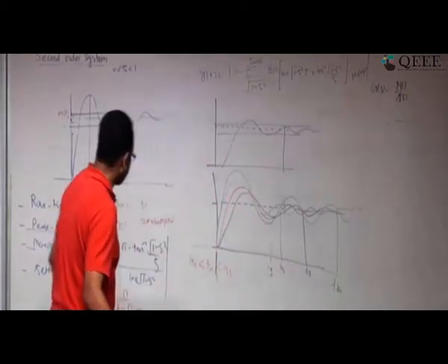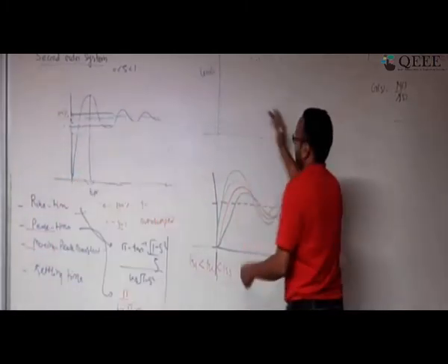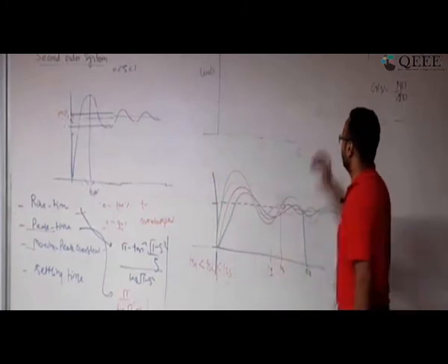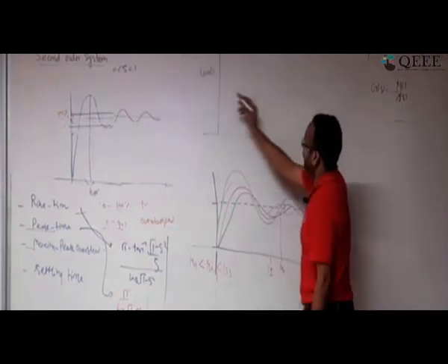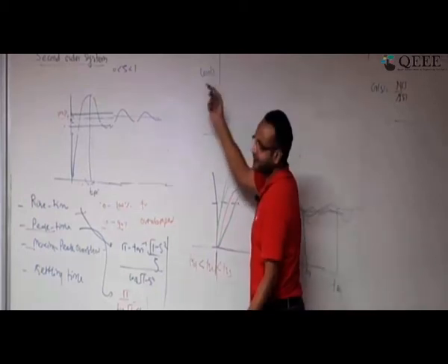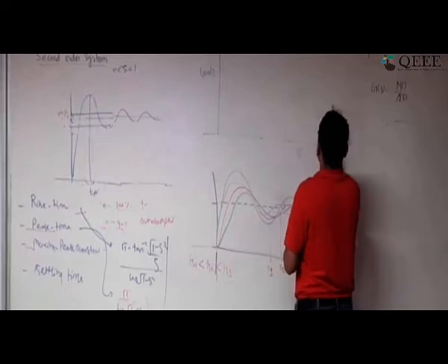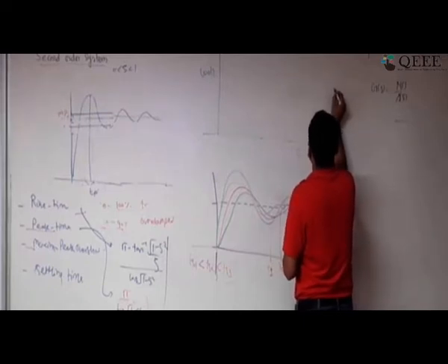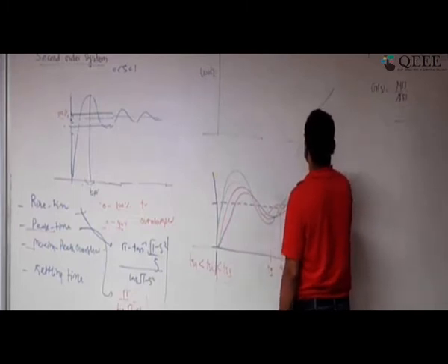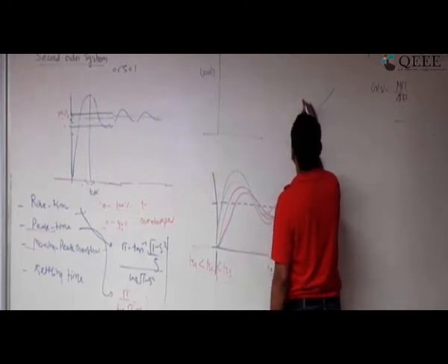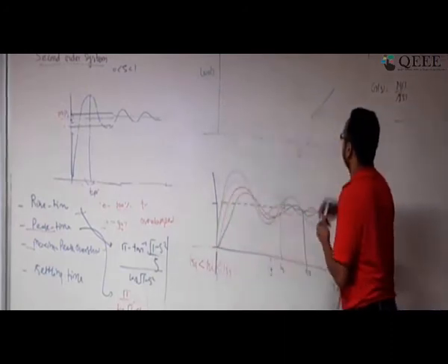So what people have observed, this is a typical plot which we have got, and if you look at it in M Gopal, you can see that this is a settling time, omega n TS I am saying, because omega n TS is a normalized settling time. So if I decrease zeta from 1 to this for some tolerance band, it will come down. Now if you reduce it further, it will go up. If I reduce it further, it will go up. So this is what I have explained to you, correct?